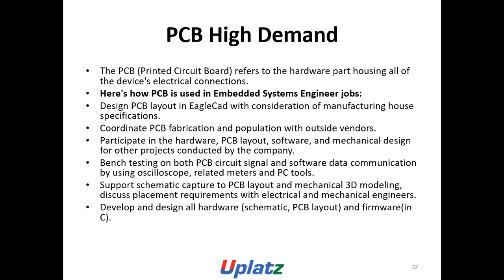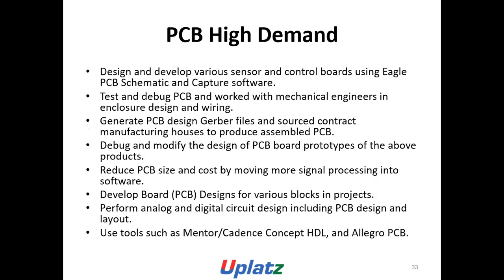Develop and design all hardware schematic, PCB layout, and firmware in C. Design and develop various sensor and control boards using Eagle PCB schematic and capture software. Test and debug PCB and work with mechanical engineers in process design and wiring. Generate PCB design, Gerber files, and source contract manufacturing houses to produce.